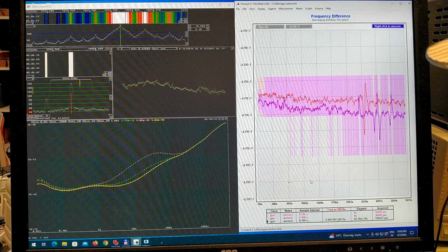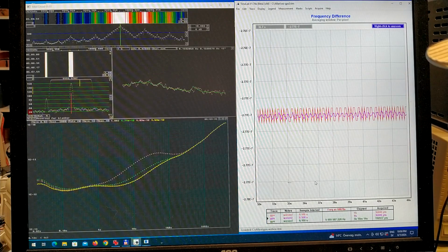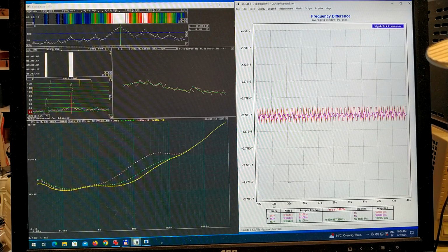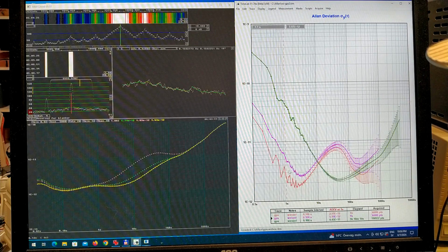Here is the frequency versus time for the two old measurements. And we can see there were some events towards the end of the measurements, and they were responsible probably for that extra peak in the Allan deviation. When I zoom in time, so I here look only at the first, at about 10 seconds, I see a very strong oscillation at this particular point in time. And that is the explanation why the Allan deviation has this structure here.